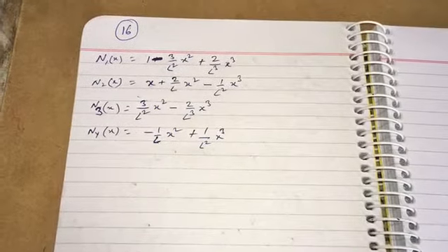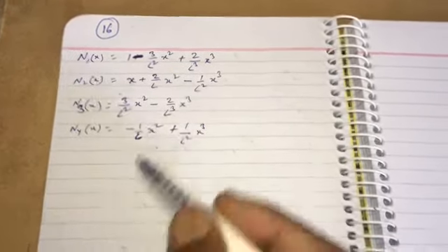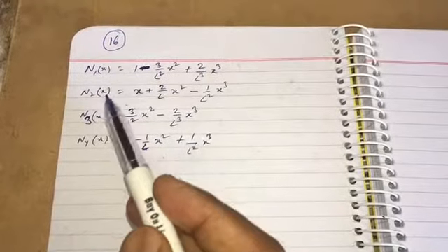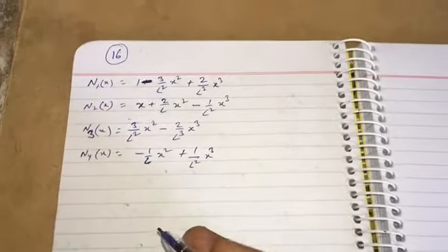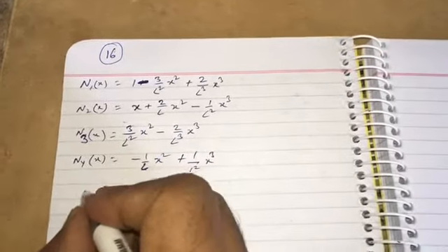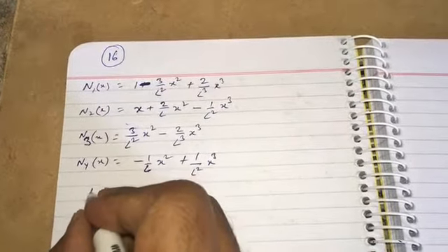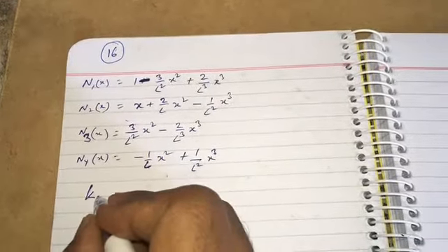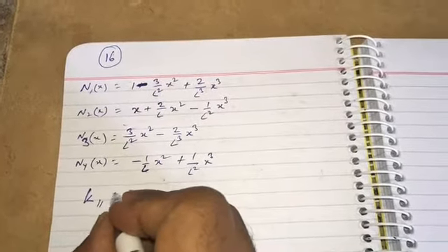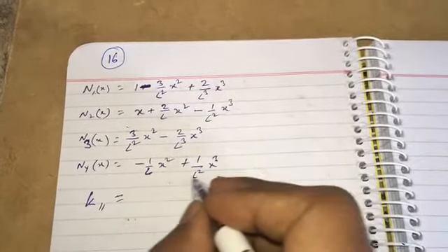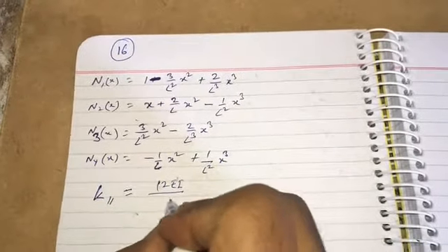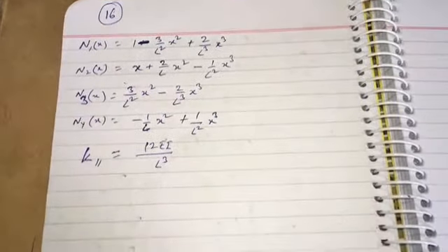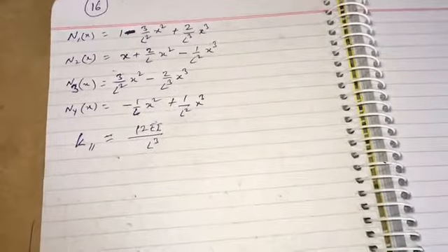Okay, so in the last video lecture we derived N1, N2, N3, N4. These are the shape functions, and we also derived the first component of the stiffness matrix, that is K11, and we got this to be 12 EI over L cubed. Okay, so let's look at